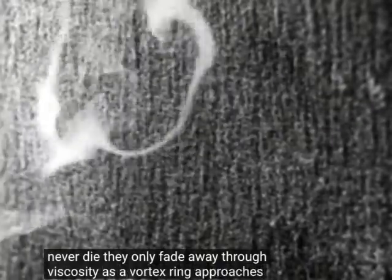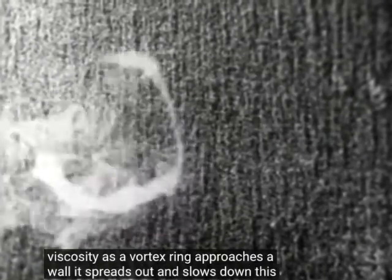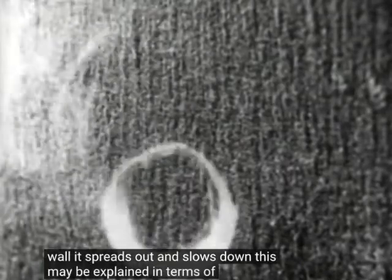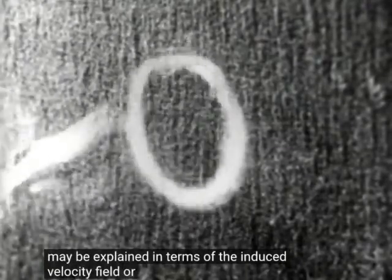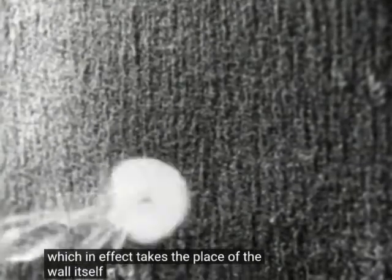As a vortex ring approaches a wall, it spreads out and slows down. This may be explained in terms of the induced velocity field of the fictitious image vortex on the other side of the wall, which in effect takes the place of the wall itself.